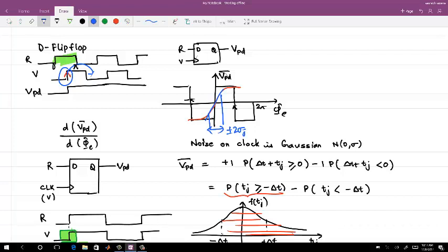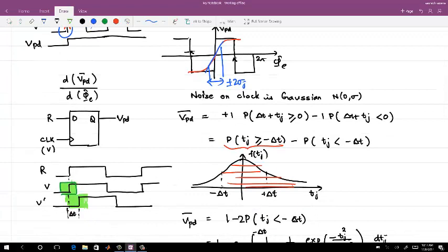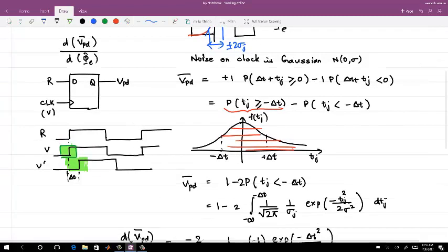You should just see that this is one single flip-flop which can work at the fastest speed possible, and it again depends what kind of flip-flop you are going to use. So the simplicity of this flip-flop is the reason why we use it as a phase error detector. And in a PLL, this gain analysis may not be that useful because this doesn't have a frequency detection capability. We will see the frequency detection capability next, but this doesn't have one.